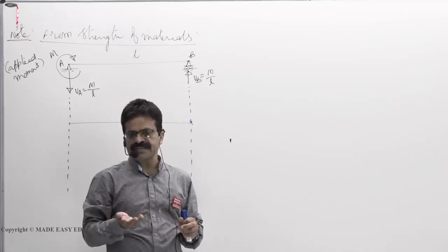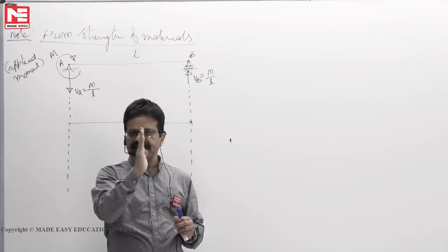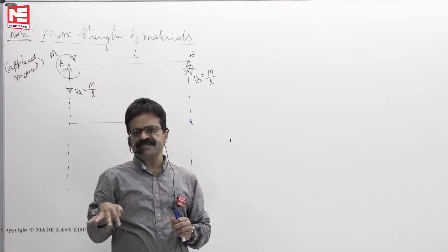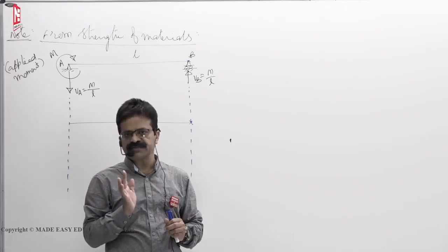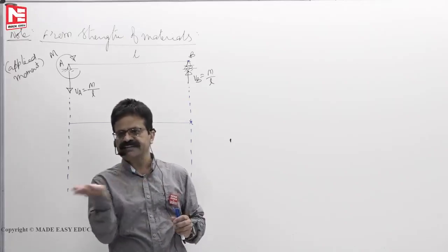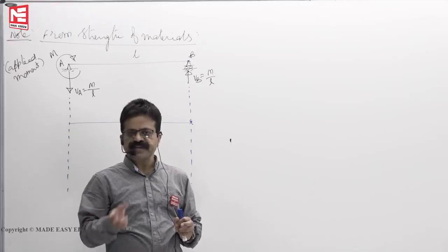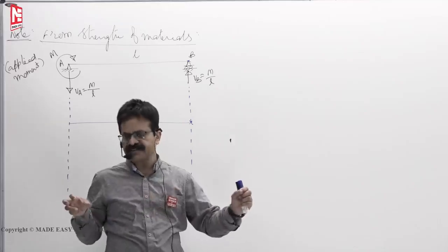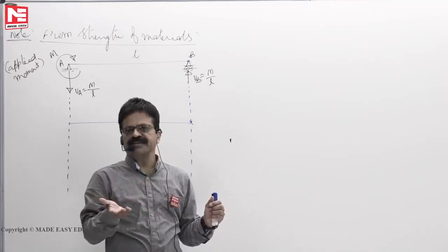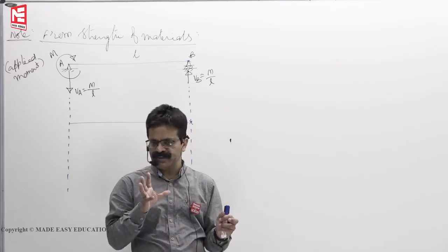Then shear force, same thing. At any section, you want to find shear force, stand there, look only one side. Unbalanced transverse forces, sum of the forces, is called shear force. Both sides, if you see, right side, left side, then what you get is sigma y is equal to 0. That is vertical equilibrium you will get. Axial force is sigma x equal to 0. That's what you have learned in strength of materials. First chapter, sigma x 0, sigma y 0, sigma M 0 you have written.